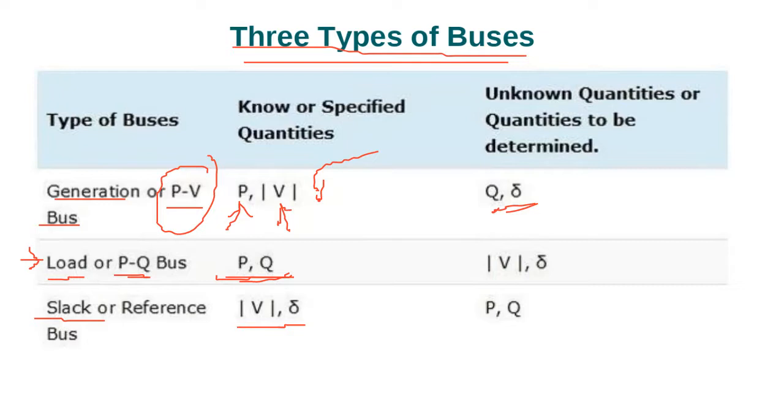So what do we have here in the power systems? We have power, P and Q. We have the voltages. We have the angle. Four parameters we need to find for every bus: P, V, Q, and delta, or V delta, P, and Q. In every bus in power systems, think of the four parameters that we need.